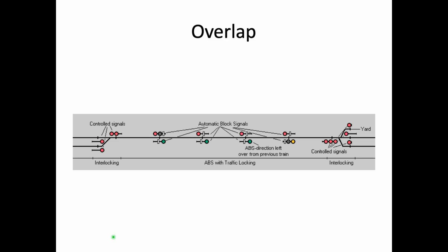I believe the last little enhancement that we'll talk about, for the basic automatic block signal systems and advanced systems as well, is called approach lighting. And you have to remember that when a lot of these systems were being installed, you couldn't take commercial power for granted. As these systems worked off primary batteries, any load you could take off the batteries prolonged their working time on a given charge.